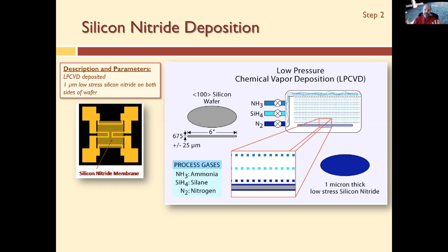And of course, any structures you make out of the silicon nitride will be stressed, and then you'll see curved cantilever beams, for example, or distorted pressure sensor membranes. Okay, so there are special processes that ensure that it's a low stress result.